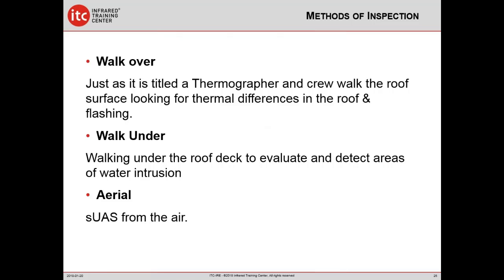One of the things that I haven't really brought up yet is in doing our homework, we should also understand whether the structure is positively or negatively pressured. This does have an impact on what we're going to see on the roof. For example, if it is negatively pressured, there's a good possibility that that is pulling moisture through the leak in the membrane and into the structure. So knowing whether your structure is positive or negative pressured is really important.